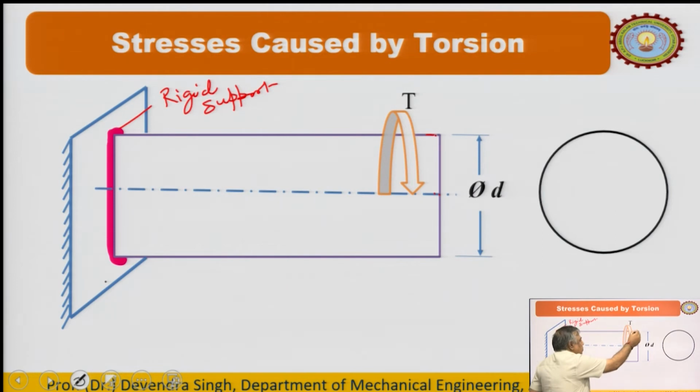So, maximum deformation, maximum slip can take place here or here, and here it is 0. Again, we are interested in keeping our elements within the elastic limit. So, again the stress is directly proportional to strain. If there is no displacement, no deformation, then the strain is 0. So, according to that concept, at the center or at the axis, the stress will be equal to 0.